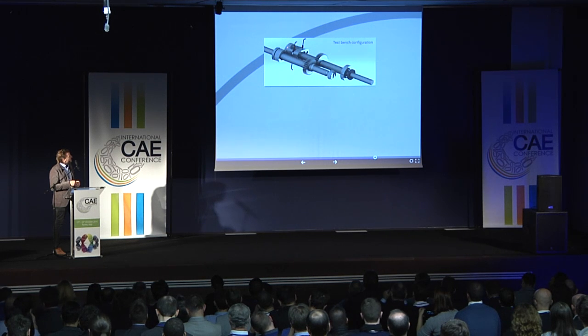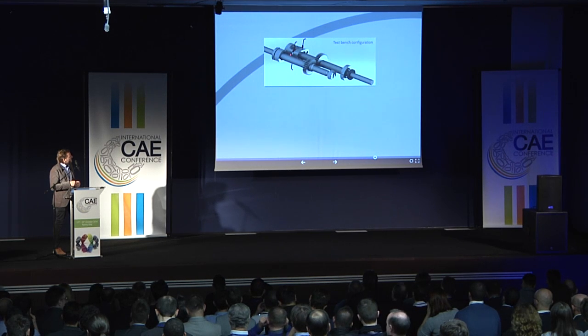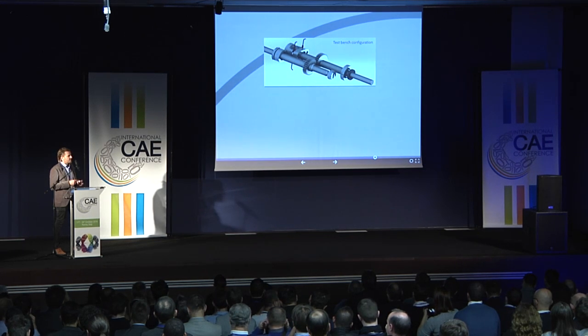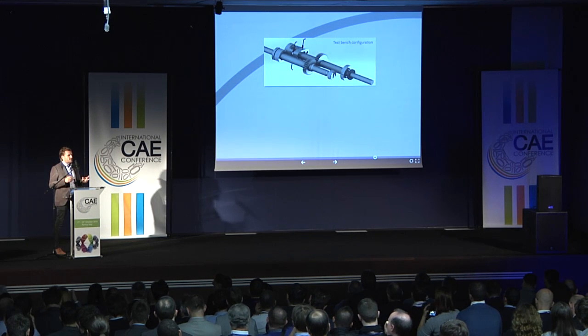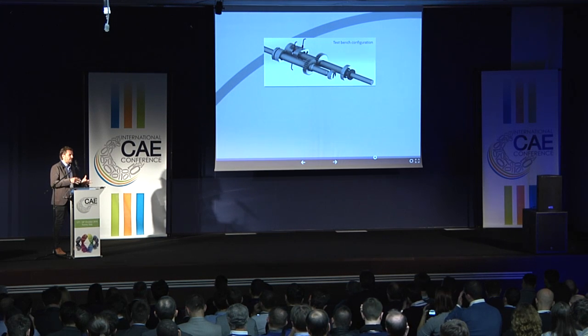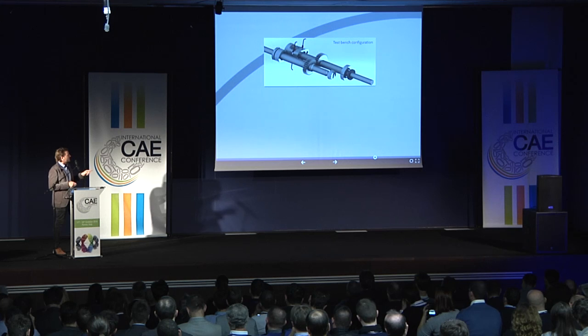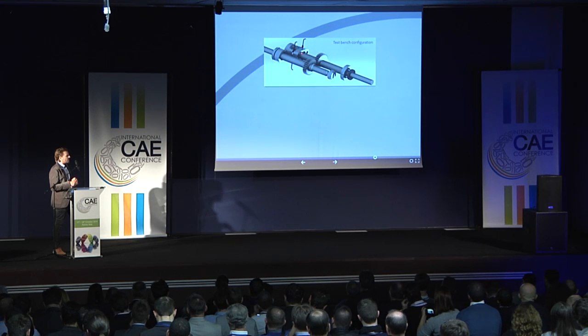The second block of steel actually contains the bearing of this shaft. So what we did is we moved the bearing from this place to this place, and right in this gap here between these 2 blocks of steel, there is sitting the piezoelectric force sensor. So we are sitting with the bearing force measurement device right in the power flow. Usually you measure with acceleration sensors. You put your sensor on your structure and you measure not directly, you measure indirectly. And this is a new approach of measuring dynamic bearing forces directly in the interrupted power flow.